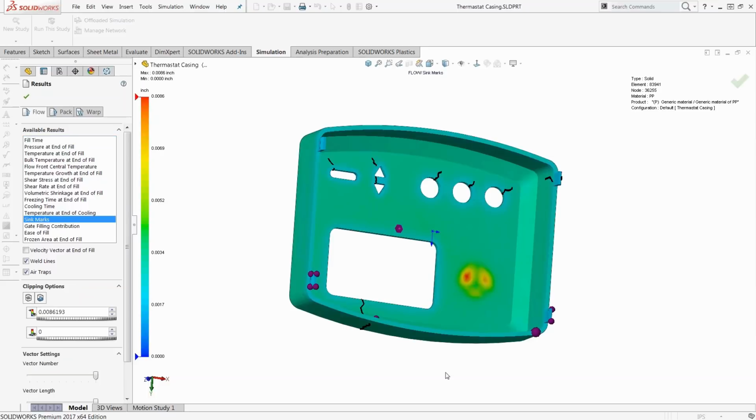Similar to that, sink marks is another one, where if you have an abrupt change in the thickness, because of the thermal profile that it creates and the longer time it needs to cool down, a sink mark is going to be generated in those regions, and you want to take that into account. Another place where you typically want to avoid structurally sensitive areas. We spoke briefly about short shots in the previous example. If the pressure in the injection molding machine is not enough, then short shots are developed, and you want to avoid these, so have adequate thickness for your parts.